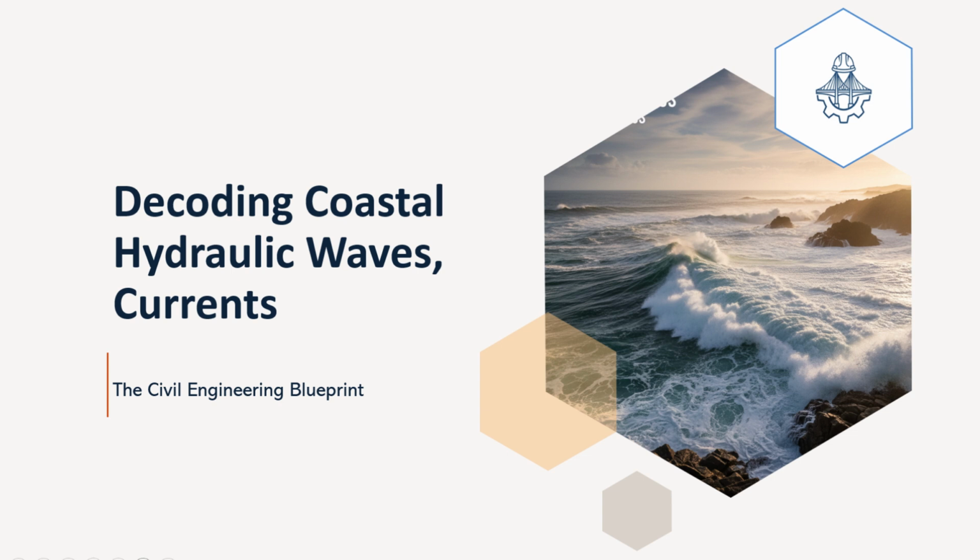This subtle but profoundly important distinction is crucial for engineers, because CG tells us the rate at which destructive wave energy is actually delivered to a structure or a coastline. The power P depends on CG, not C.